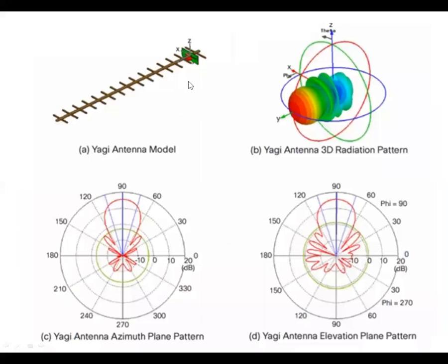This is another type of Yagi. You'll see this a lot in VHF single sideband because 2 meters is much smaller than 40 meters. Obviously, the elements are much smaller, so you can make a pretty structurally sound multi-element Yagi for very good and tight directional concentration of your signals.